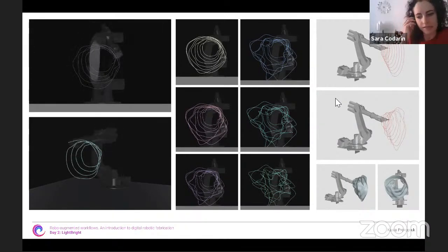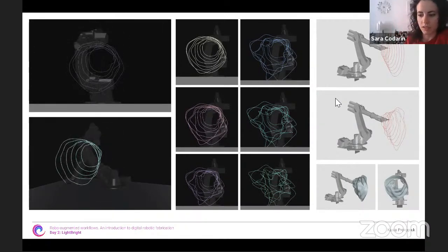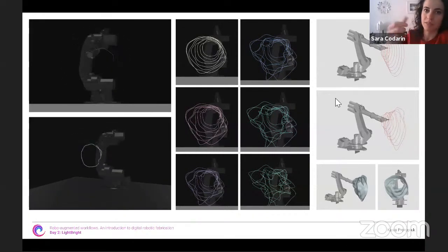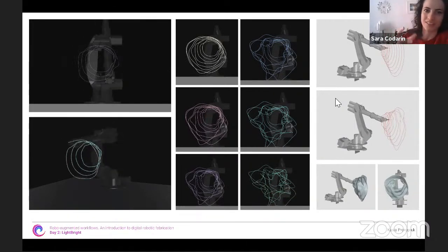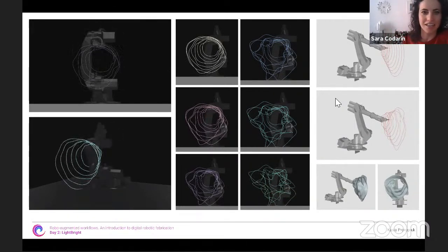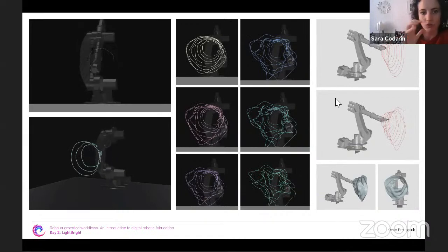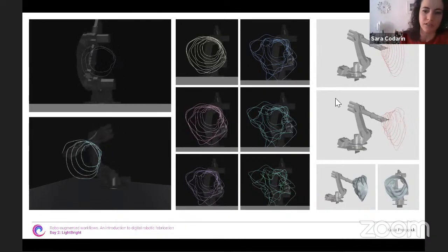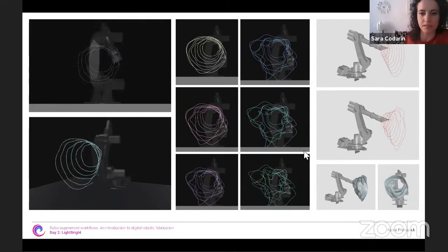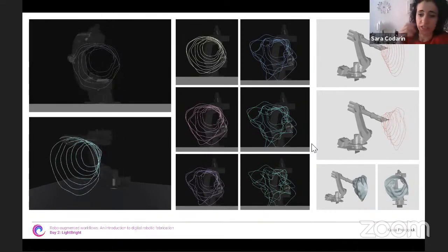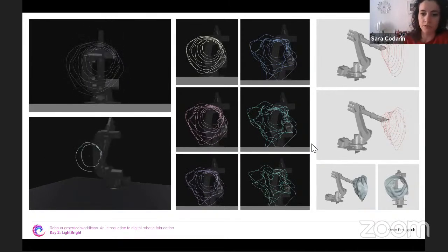So sometimes in KUKA PRC, the toolpath that you see is an approximation. And so sometimes some tweaks you don't really see as a preview because it's just machine computation, let's say. So you don't have full control over that, but it's close enough. Yeah, let's try. So I changed your mode into point to point. It would be interesting to see this iteration.